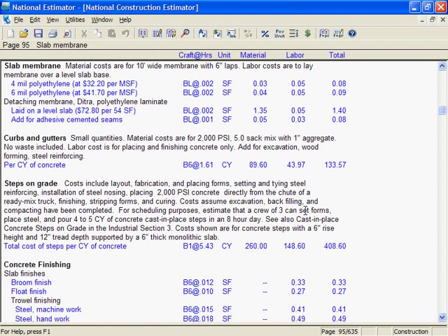Your default Costbook opens automatically every time you begin using National Estimator. The last Costbook installed becomes the default. For me, that's the Construction Costbook. But that's easy to change. Save time by changing your default to the Costbook you use most. Now, here's how to make that change.